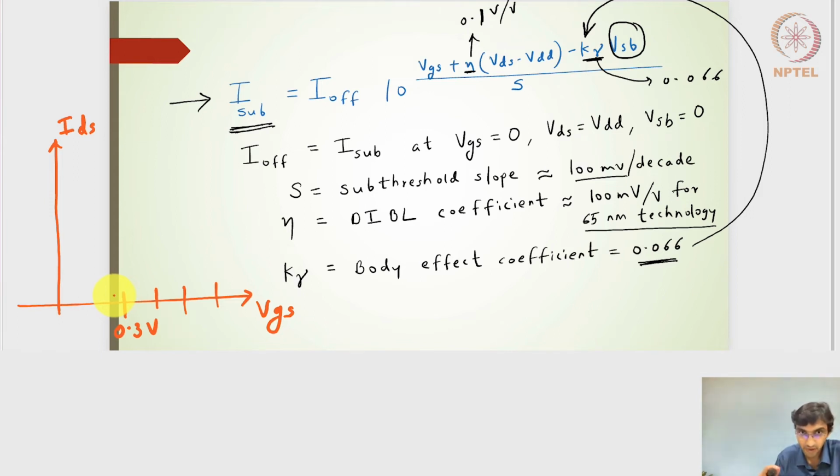After the channel is formed, I'll get some amount of current based on the VDS value, and if the VDS value is more than VGS minus VT, I'll get the saturation current. So let's say the transistor is in saturation, and I'll get some current here, and it will be VGS minus VT the whole square. So I should have a square relationship, and these are those points.